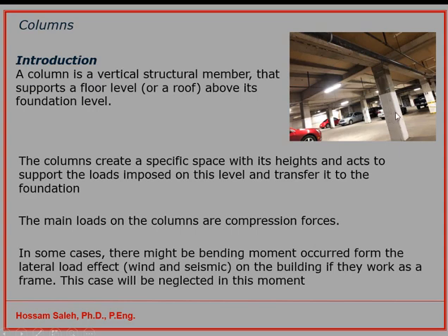Now, if you look at this column here, the column is the member which provides us with the space to work in. So the column is supporting a floor or a roof, and that provides us with space to use. Normally the loads on the columns are compressive force, unless the building is subjected to lateral loads that can come from seismic and wind. If there are no shear walls within the building, then they can have frame action, and these columns can see some bending moment, and the loads will not be only compression force.